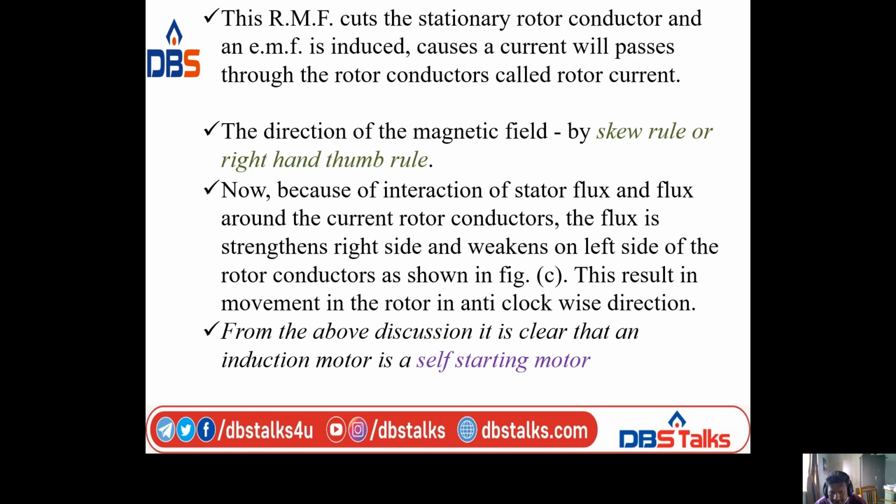Now because of the interaction of stator flux and the flux around the current conductors, the flux strengthens on the right side and weakens on the left side. That means they develop some force on the conductor. The turning moment of the force is nothing but torque.